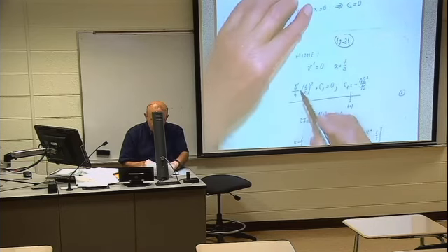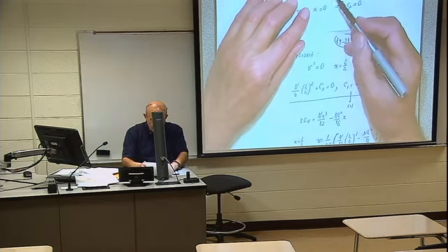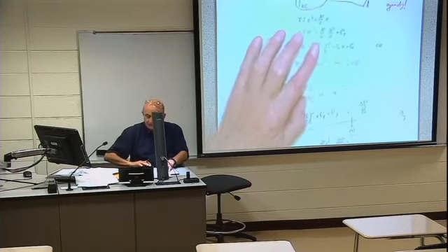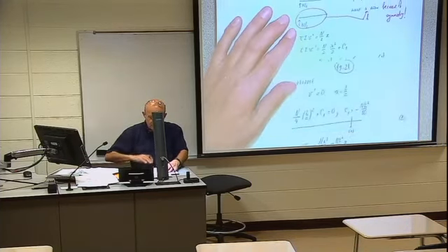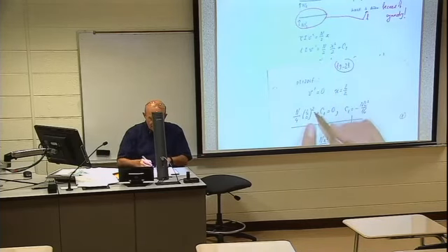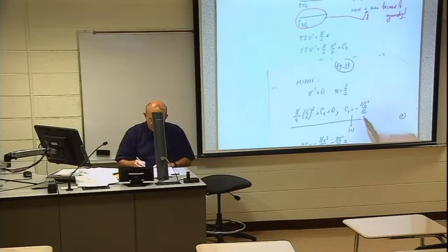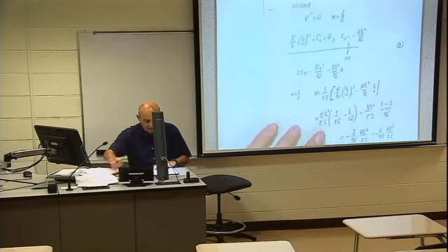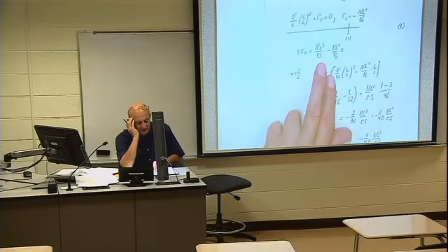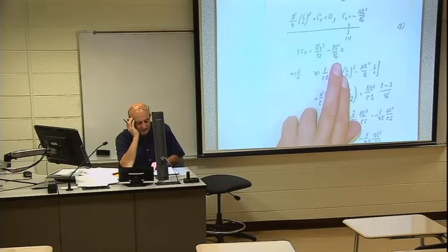So we will have n over 2 times 2 is 4. So n over 4, L over 2 squared plus C1 equals 0. C1 equals, then this L squared over 4, 4 times 4 is 16, minus n L squared over 16. So the equation becomes like this, EI V equals n x cubed over 12 minus n L squared over 16 x.